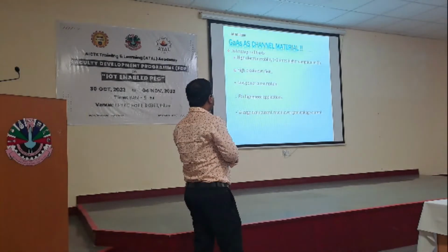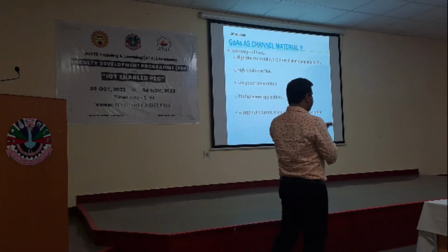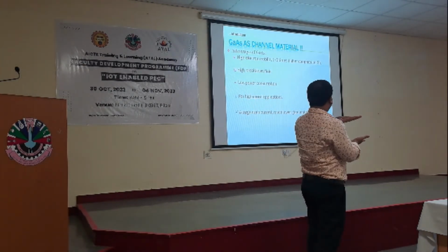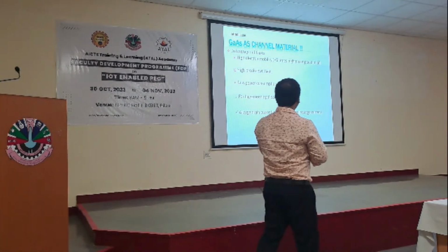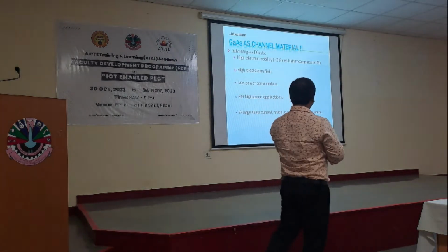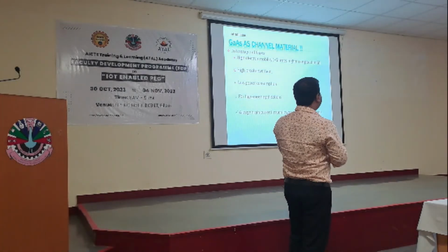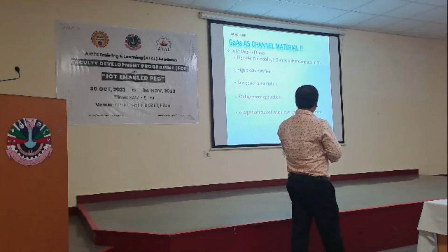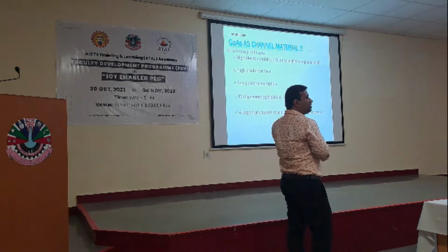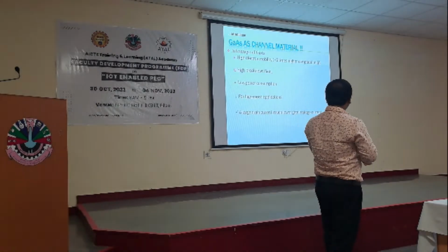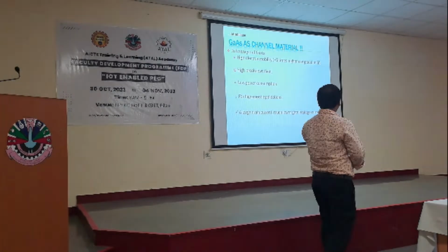Now, as I told initially, it is a gallium arsenide MOS, meaning metal, then oxide layer, then the third layer is gallium arsenide. People have used it as a channel material. Why is it used as a channel material? Because of this extraordinary property: it exhibits high electron mobility, at least 5 times greater than silicon.